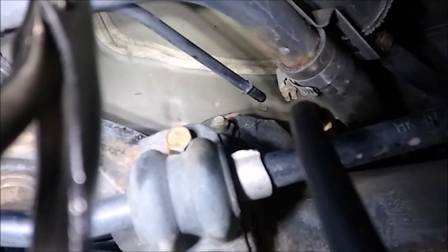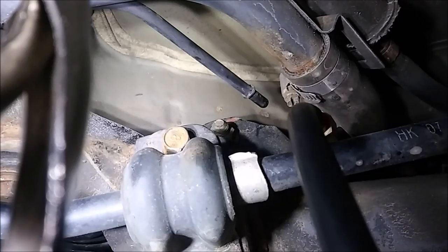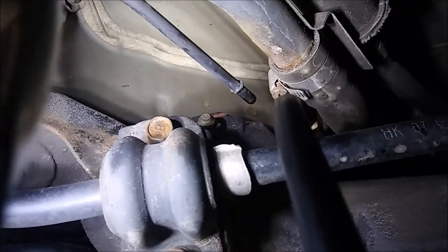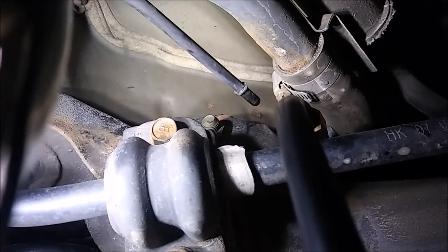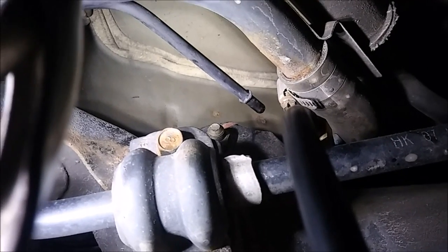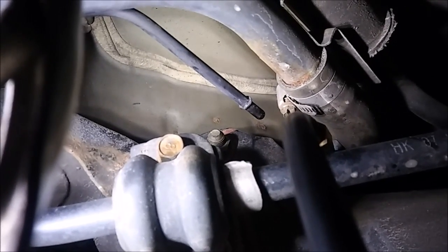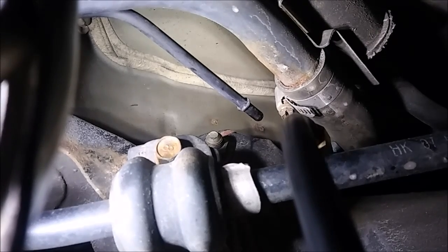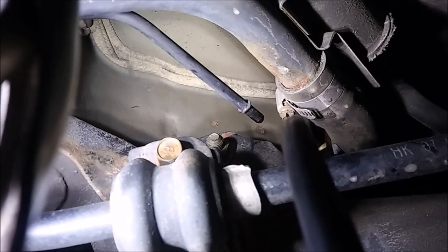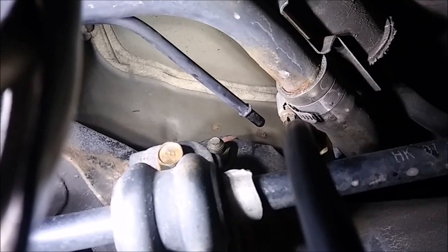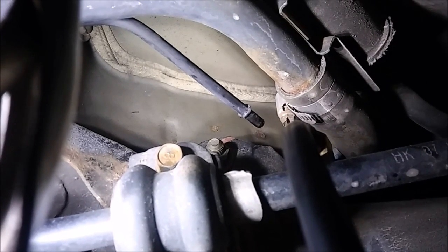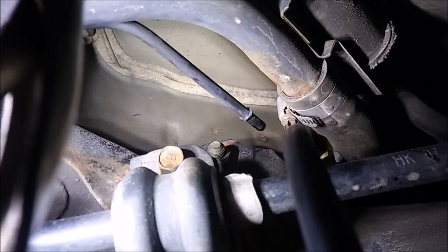What we're now going to do is watch this hose up here, the one we disconnected. This goes up to the filler neck. It's for the ventilation for filling the tank up. What I'm looking for is smoke to pour out of it. When that happens, we know that we have good smoke in the system, and then we can cap that off and start hunting around for a leak. So just watching it. This may take a little bit, guys. There's a lot of air in these systems to account for when you're smoke testing.